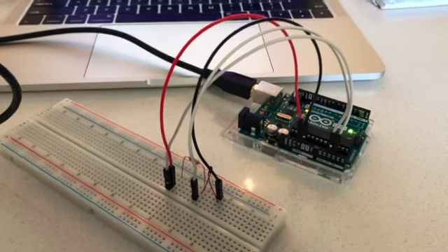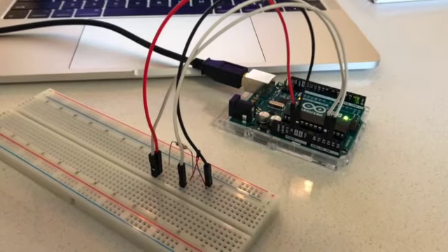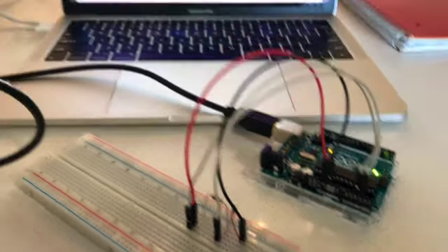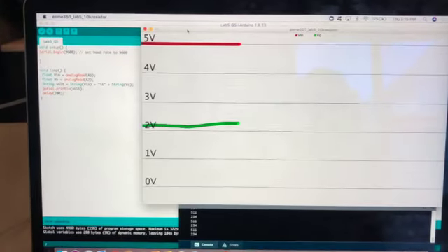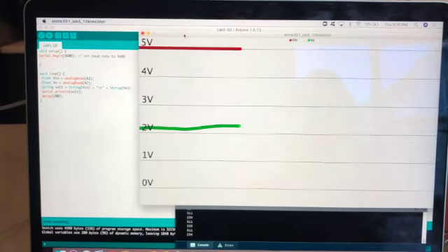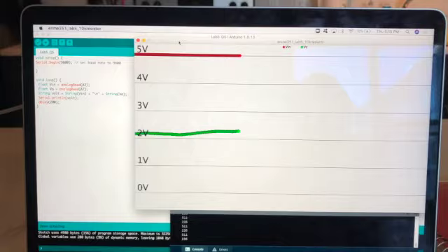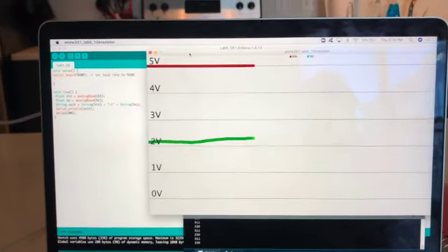This is my circuit for the thermistor. The sensitivity is maximized when the resistance is even on either side of the voltage divider. So because from the datasheet R0 is 10 kiloohms at room temperature, the resistor needs to be 10 kiloohms. In my Arduino code, I set the baud rate to 9600. I'm reading the voltage input and voltage output and printing it to the serial monitor.